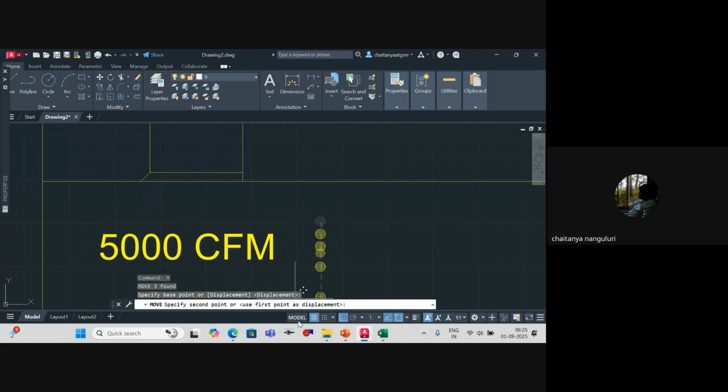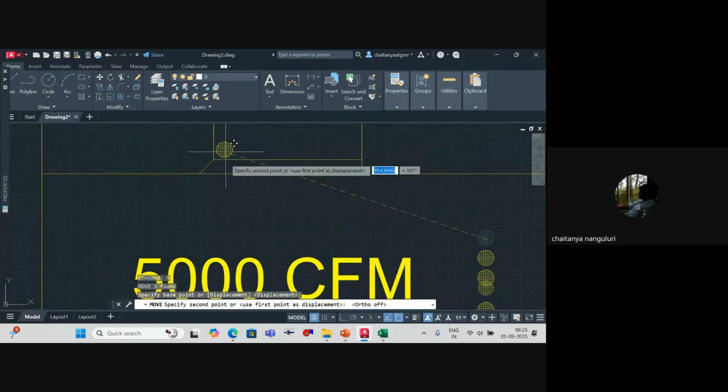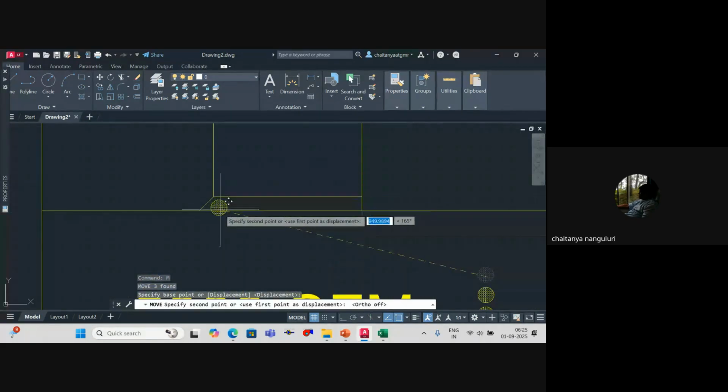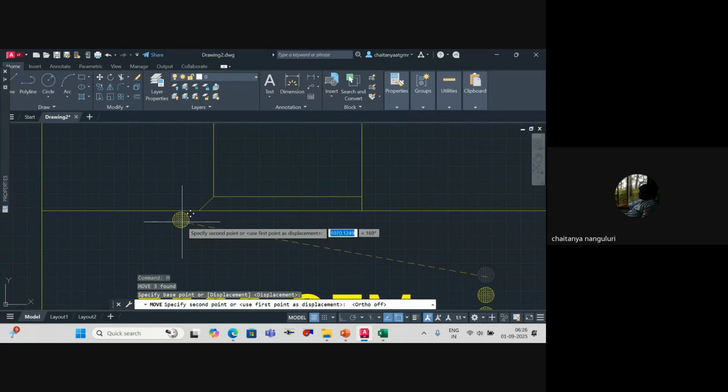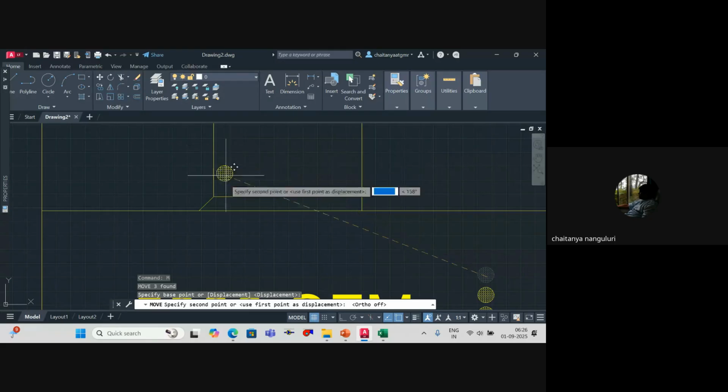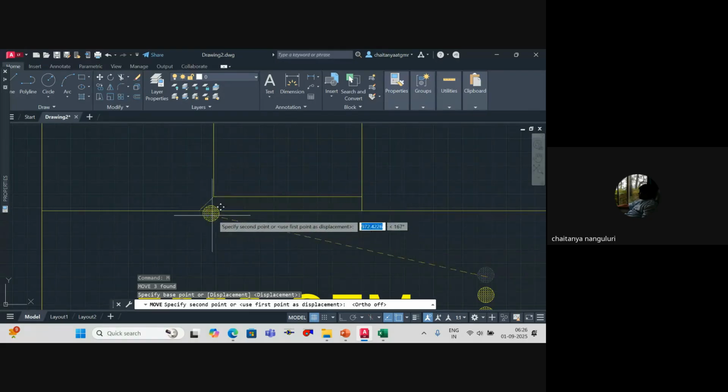should come out. So when it comes out, do you think suddenly it can directly take a 90-degree turn? No, there should be some inertia, right? So to give space for that inertia, you use your effective volume and will provide the shoe piece. That means the airflow will go something like this and then it will enter. That additional space is required for the basic inertia of air because it has to change its direction. Understood or not?